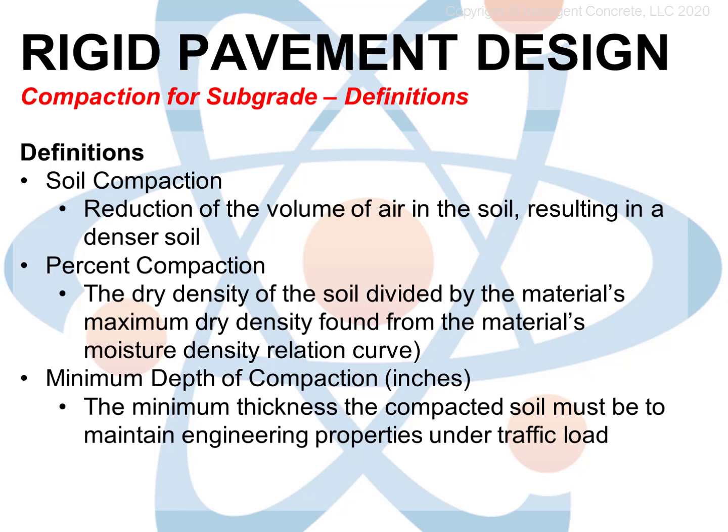Typically, it's expressed as a percentage of a Proctor density. Proctor densities are tests that are performed in a specific way against known parameters to give a standard measure of how dense a soil is. Buildings usually use what's known as standard Proctor, and 95% density is a typical specification.